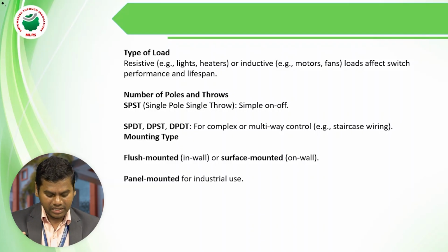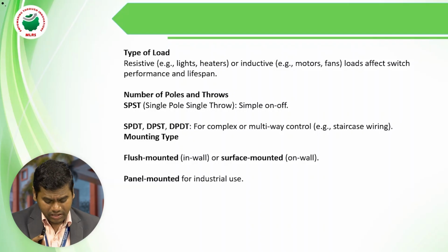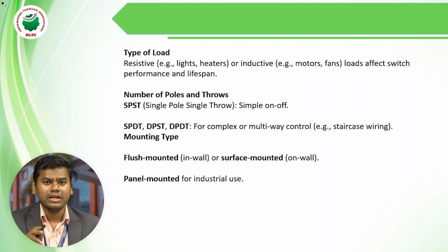First, SPDT is single pole double throw, second, DPST, double pole single throw, and third, DPDT, double pole double throw. These, SPDT, DPST and DPDT, we are using for complex or multi-way control, for example staircase wiring and mounting type cases only. We are using these three.